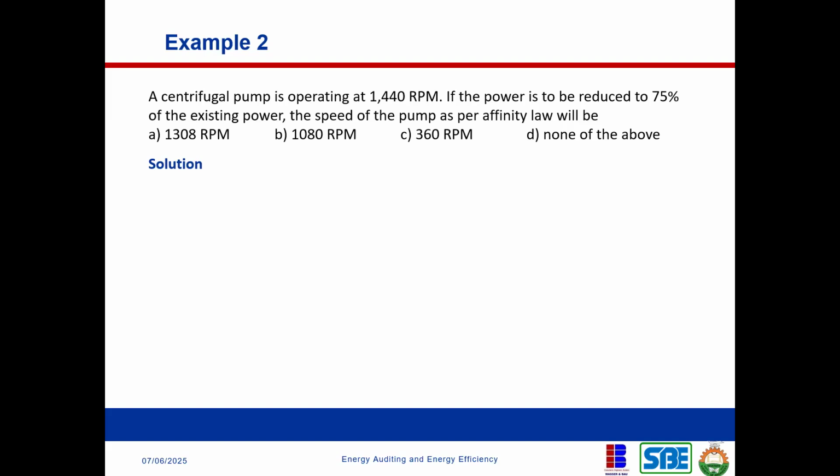So for example, if you go to an industry and they are pumping 9,000 meter cube per hour, and the pump essentially can do like 30,000, but the highest that this industry has done is 9,000, but that pump is designed to do 30,000. In that case, you can advise the proper dimensioning of that pump. And how do you advise the proper dimensioning? By doing some of this calculation. So you can say, okay, based on the height you're pumping and the flow rate that you're pumping, this is the pump that I think is ideal for this process.